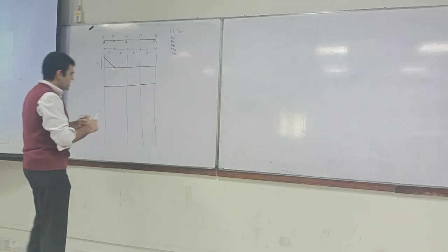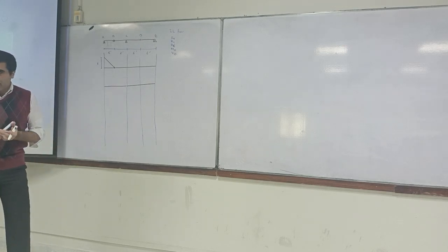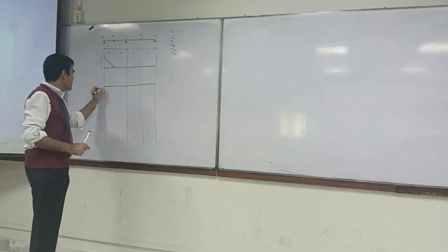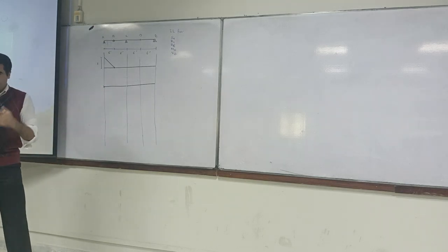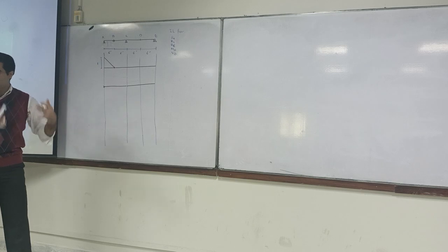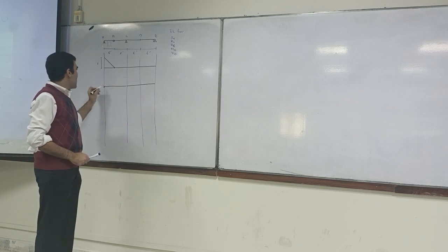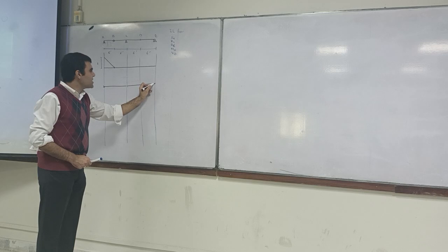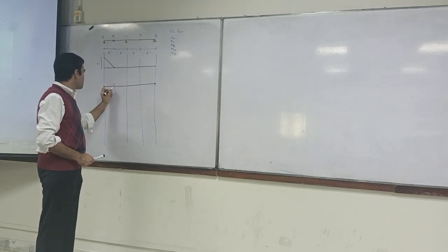The best thing is that first of all, let us allocate those points which are not going to move. We have this point, it should stay over here because it's a support. The supports are sort of kinematic conditions, so other conditions must be complied with. This one will not move, this one cannot move, and this one can move either up or down.